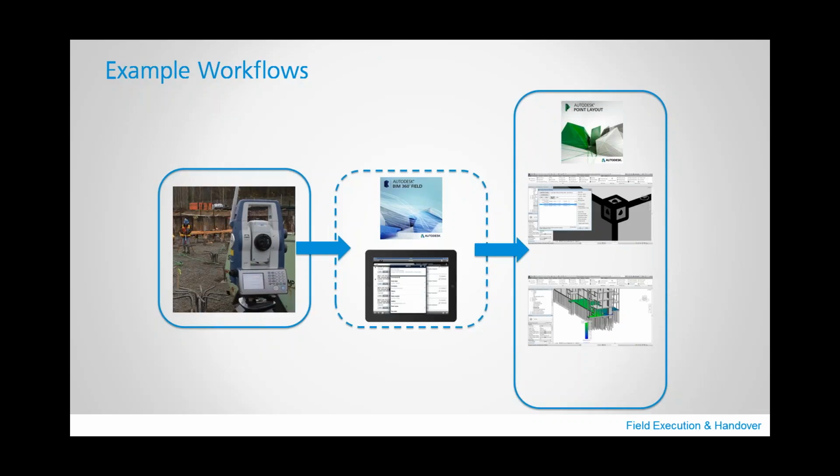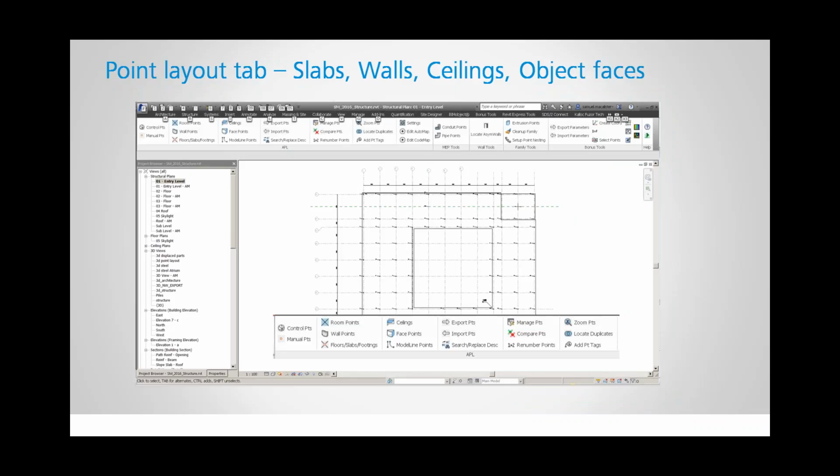We can survey it with a laser total station here and get accurate information and then feed that back into the Revit model. So if we're still doing the lean construction, the just-in-time information, and we're still doing our partition layouts, we can use that information to make sure that where we're setting that next partition out from is exactly correct with what's been built with the structural components.